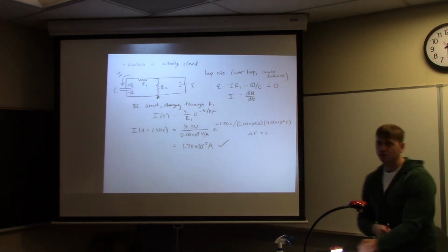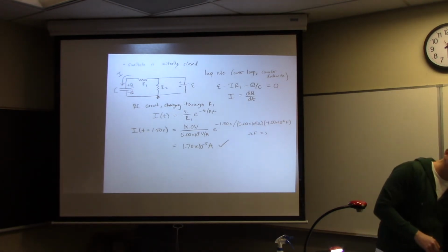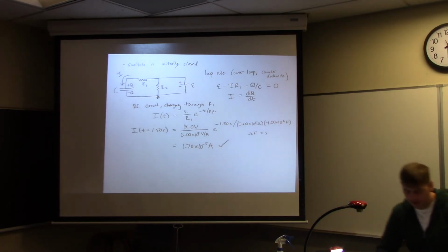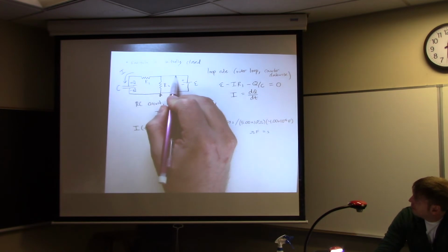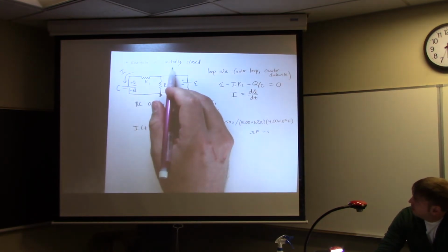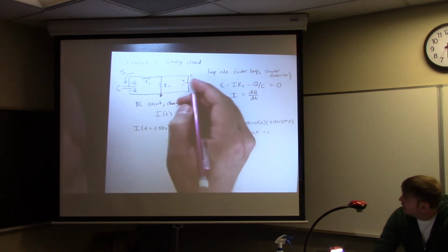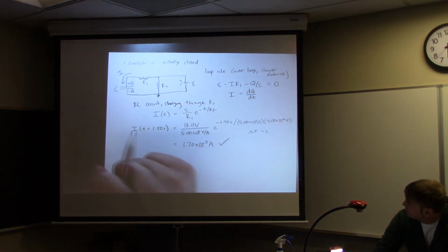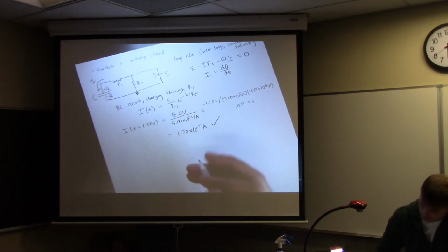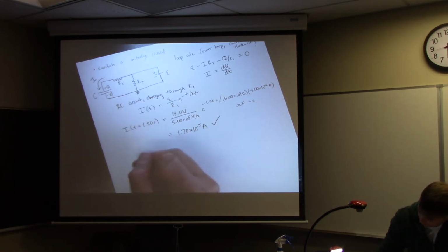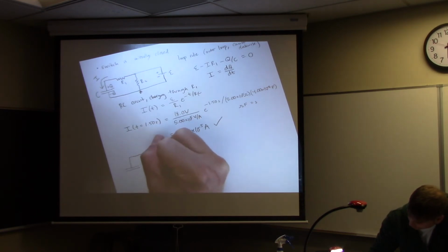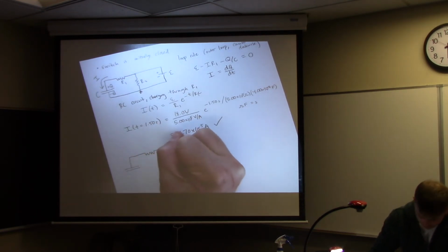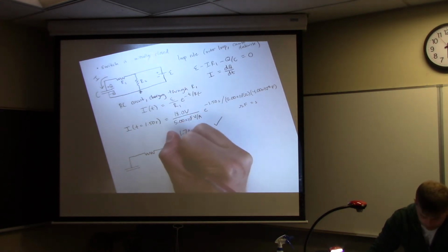So we have to think carefully about what the circuit looks like when we reopen the switch. Because the switch, if you recall, is right up here. Okay? And if I open it, I'm basically disconnecting everything on the left side from the battery. Okay, so all that's happening at that point is the only place that we can have any current flowing is in this leftmost loop of the circuit. So here, let's just draw that part of it. So that's all that matters at this point.